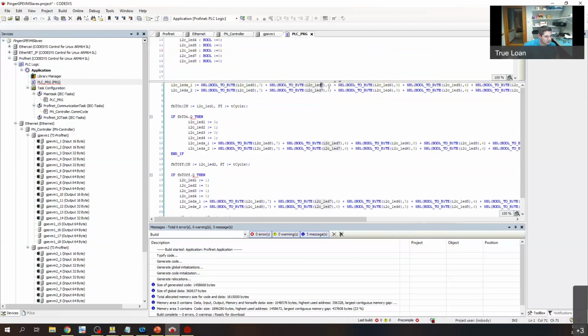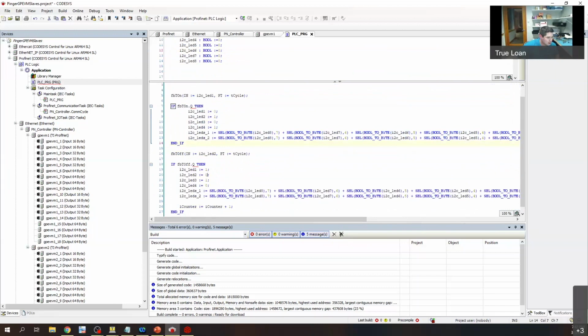Number 7 here, we're going to shift over 6, yada, yada, yada. And then delay for a certain amount of time. Then we're going to rewrite those bits with 0101 data, store those back into the byte, and then we're going to flip it with 1010 data. So we should see an LED pattern on the two slaves or secondary boards where the lights kind of shift back and forth together. Let's go ahead and see what that does in action.